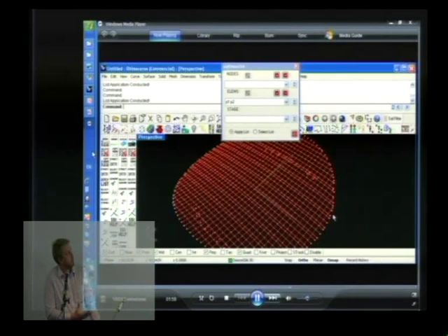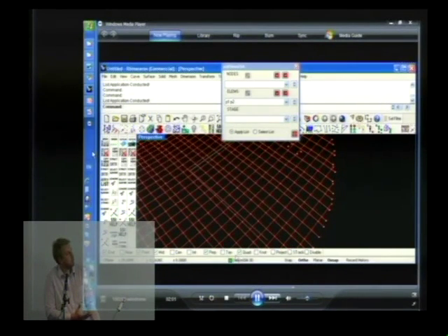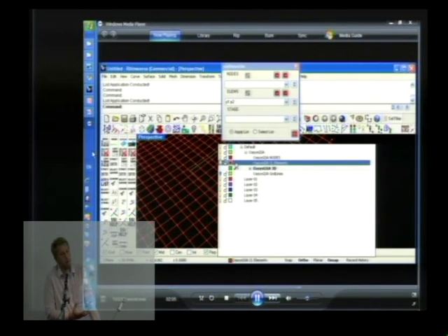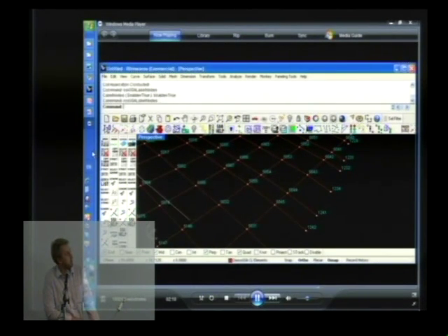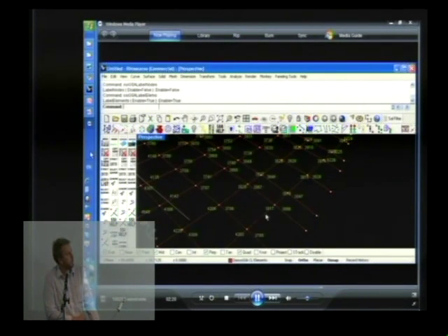And traditionally, the means that have been used for trying to convey your model from one program to another has simply been a wireframe or centerline DXF or DWG file. But then if you've assigned your materials, if you've assigned your cross-section profiles, if you've assigned intelligence to the model you've created, that's all lost in using a primitive DWG format.